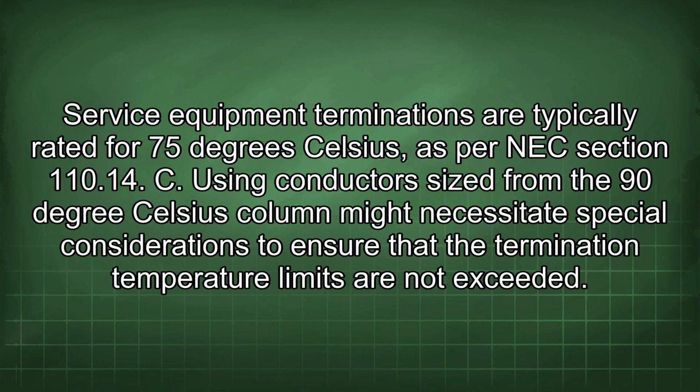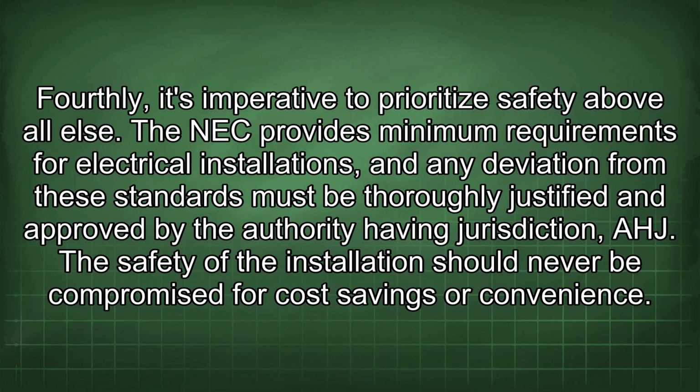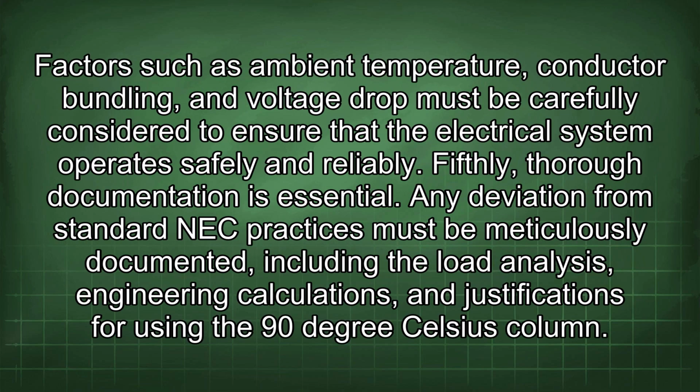limits are not exceeded. Fourthly, it's imperative to prioritize safety above all else. The NEC provides minimum requirements for electrical installations, and any deviation from these standards must be thoroughly justified and approved by the authority having jurisdiction. The safety of the installation should never be compromised for cost savings or convenience. Factors such as ambient temperature, conductor bundling, and voltage drop must be carefully considered to ensure that the electrical system